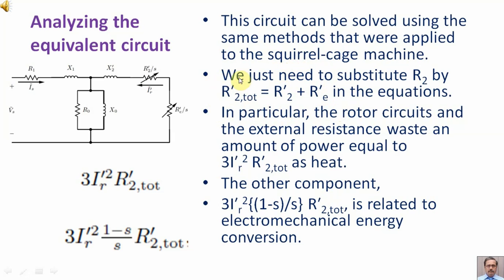In particular, the rotor circuits and the external resistance waste an amount of power equal to 3 I'_R squared into R'_2 total as heat.